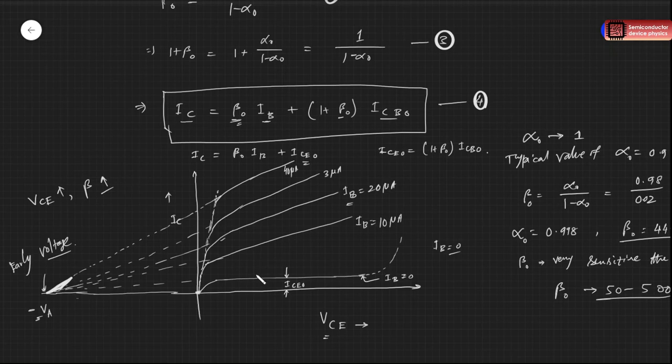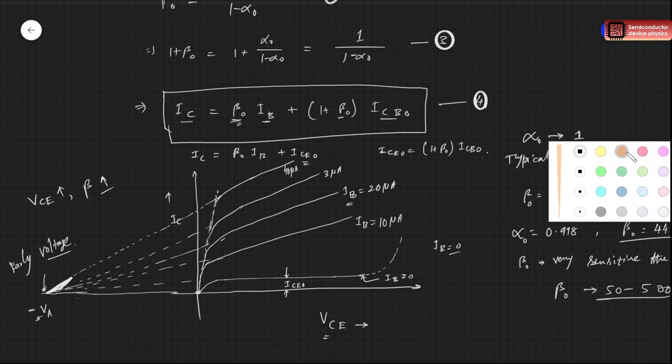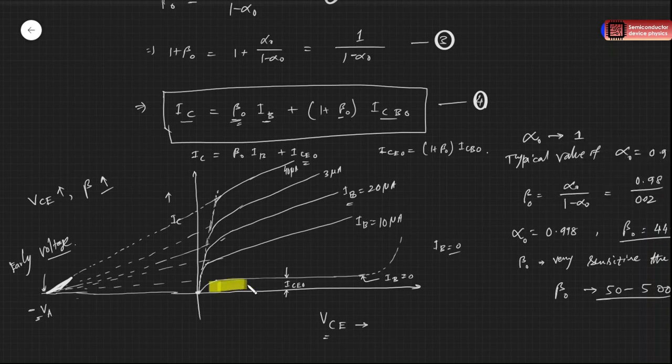And in this transistor, if you see the different bias mode regions, right? Here we have the saturation and cutoff modes. This region where the IB is less than 0, that means we are applying a reverse bias to the input terminals. So this is our cutoff region.